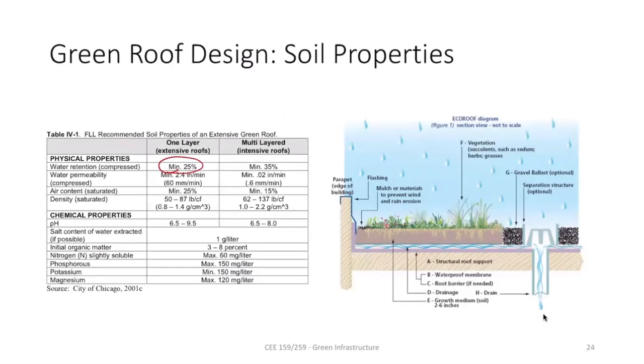And it has to have some permeability. It should not be so impermeable that most of the water stays as ponding. Also you don't want to have high permeability because then it drains everything out and you have to again irrigate for that. It has to be breathable. That means the air has to have high amount of oxygen for microbes to grow and the root structure to be healthy. That's why the air content has to be also high. 25% will be air.